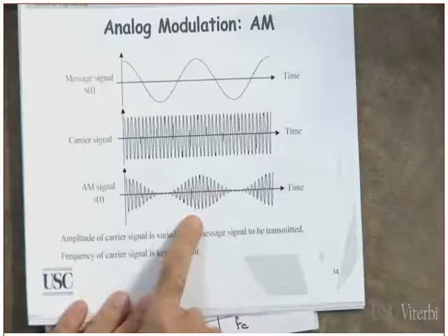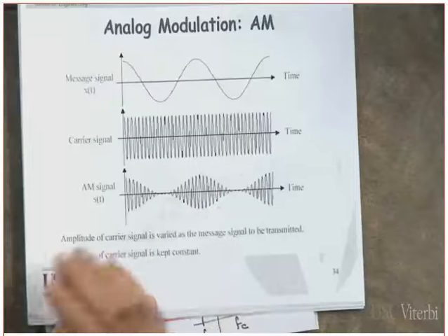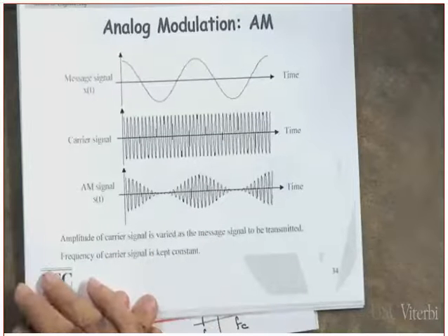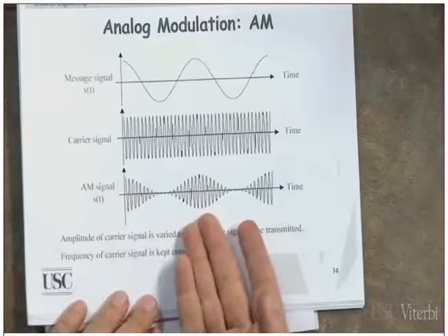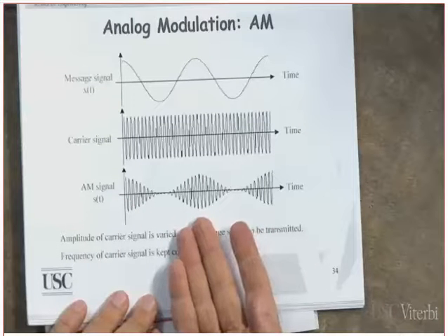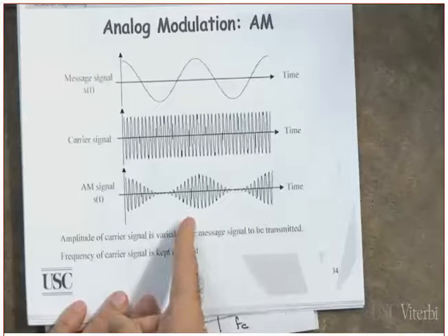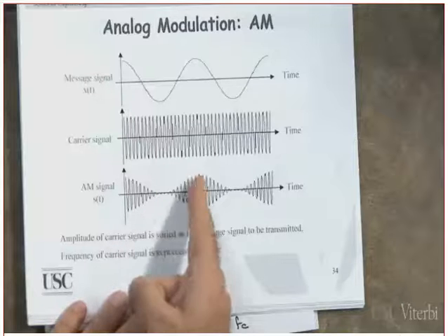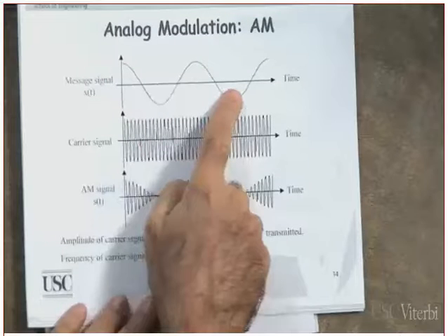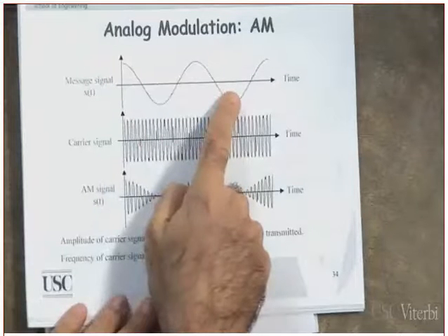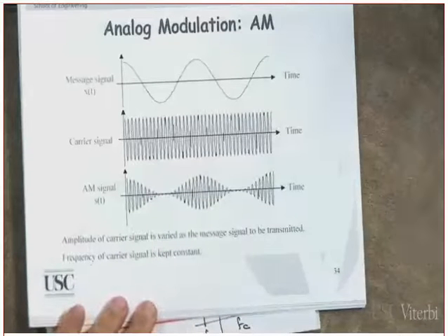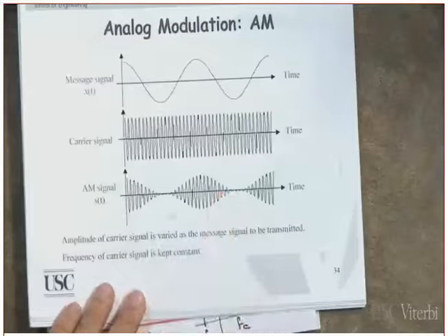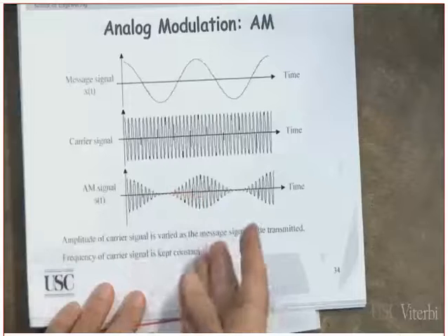Okay, tell me, what did I change here? I changed the amplitude. Are you following me on that? You can see right away, this is a type of modulation which is called what? Non-constant envelope. Is the envelope constant or non-constant? Non-constant. I want you to see the envelope. Does it follow the modulating signal? We will see that we can detect it with a demodulator. This is a very simple what? Envelope demodulator. Later on. But did you get the idea?